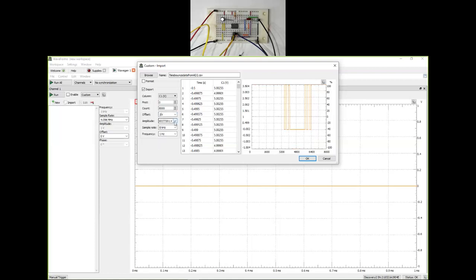And amplitude also needs to go to 2 volts and frequency of 4 hertz. Okay, so this way I have a wave that goes between 0 and 4 because of amplitude 2 and offset 2, and that repeats every 4 seconds, 4 hertz, so quarter of a second.